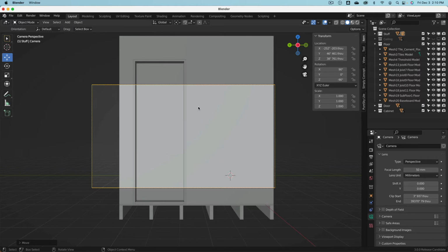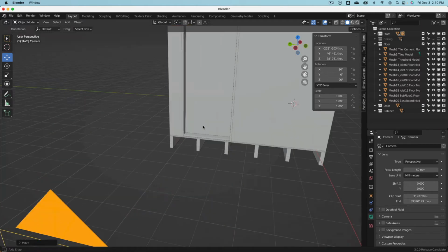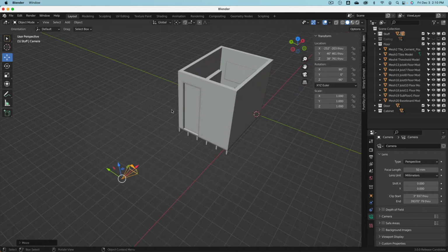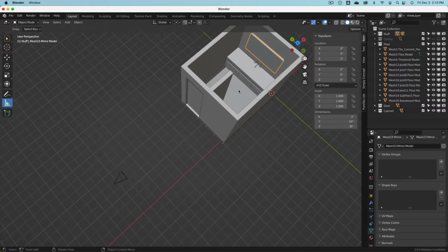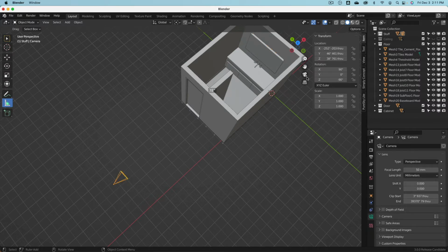Also, how can I very easily center this camera left and right? Well, there are two ways to do this. Everything grows from the zero point there. So I could go ahead and measure, for example, from here to here, 78. So 78 divided by 2, 39. So you should be along the y-axis at 39.